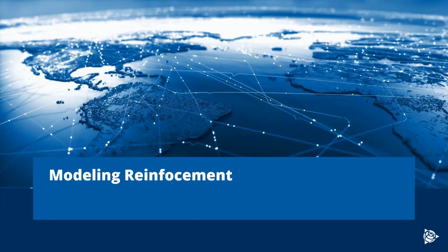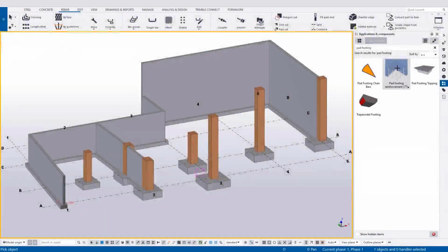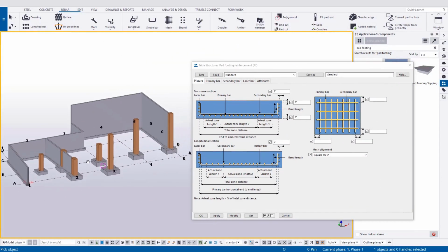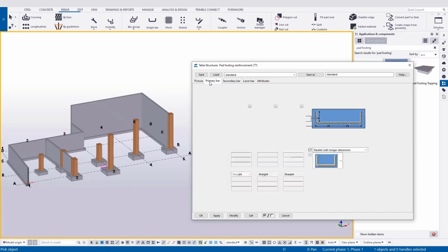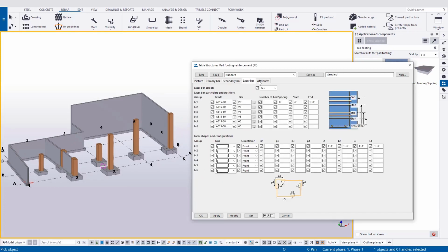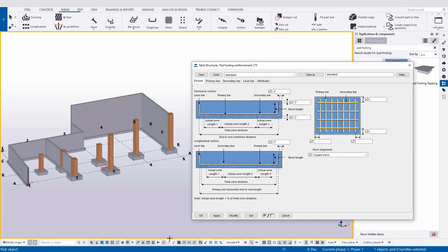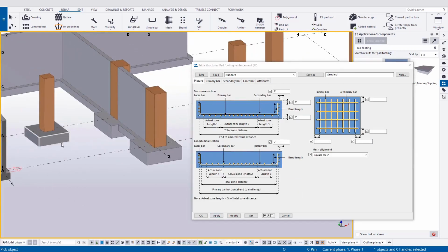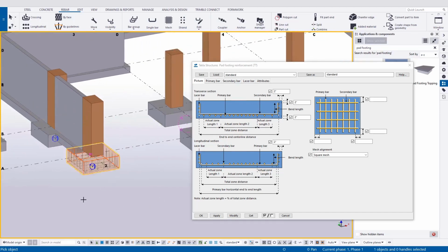We have a couple of methods, both are excellent and provide their own advantages and disadvantages compared to the other. First, let's take a look at components. We can choose to populate reinforcement through components that perform multi-step functions and are more often controlled by options and fields in a dialog box. They use native Tekla tools, such as the rebar tools found in the ribbons, and help expedite placement and configuration. Users can specify the parameters in the dialog box and then apply the component to the model.